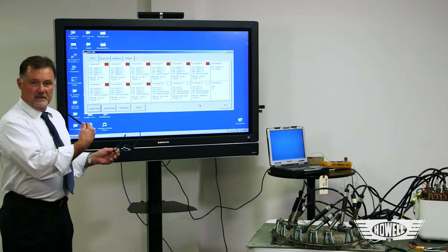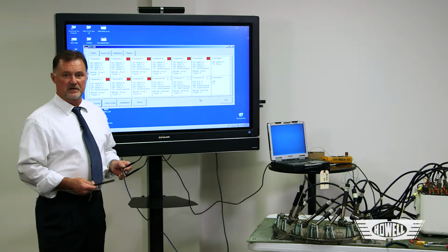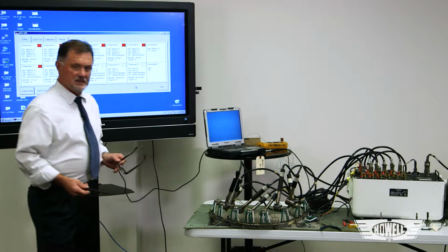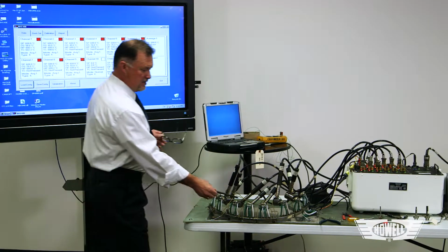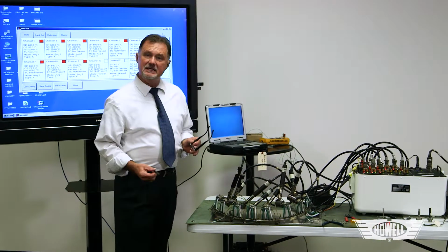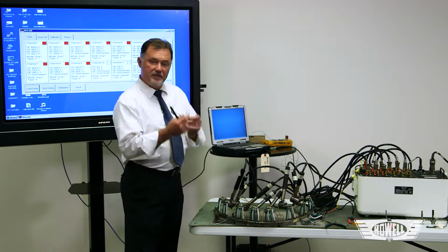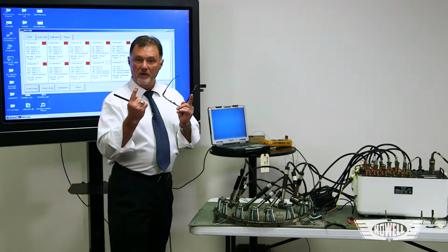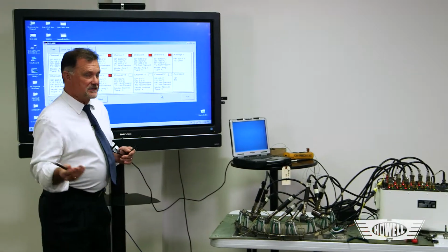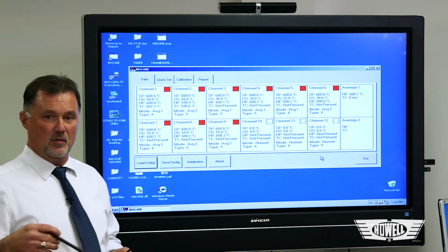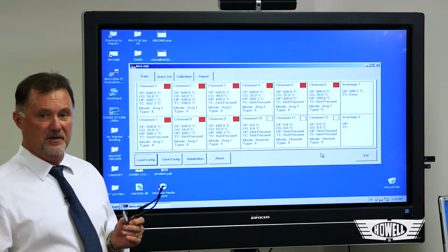Okay, so we had 9 thermocouples all reporting at 600. So we've selected thermocouple number 4 in the system, and we have disconnected the alumel lead to the TIT indicator circuit. So this is simulating as if one of the thermocouples internally had broken and became open. So we were at 600. Now if we look, we're at 602.3. So with an open, we literally went up 2.3 degrees.